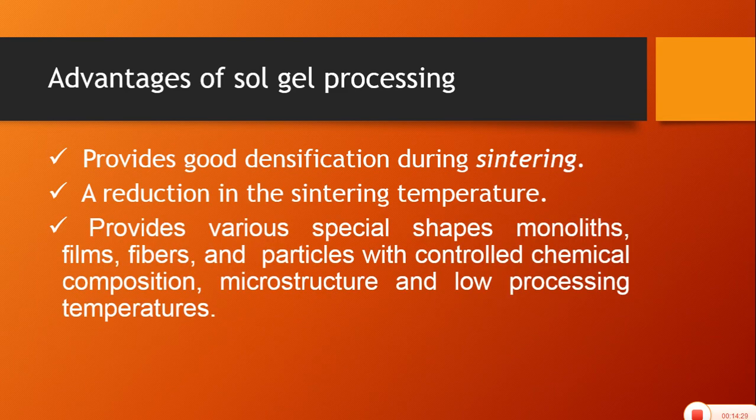Most gels have an amorphous structure even after drying and contain fine pores. Either it is a particulate gel or the polymeric gel, both usually have an amorphous structure. If a dense ceramic is required as the end product, meaning we need a dense product or a crystalline material, these characteristics are very favorable. That is the amorphous structure and the fine pores. They are very favorable for good densification